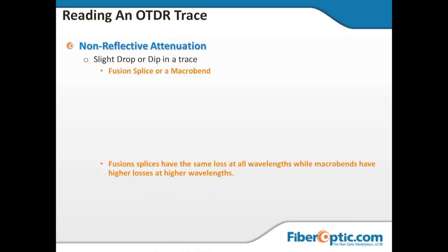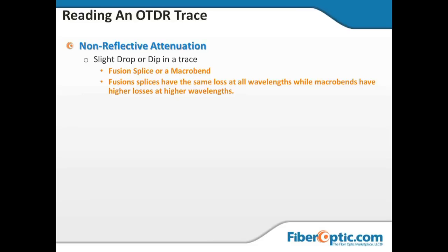And that's why a lot of the construction testing that we do behind splicers and construction people, when we're called out to do that kind of testing, is we will shoot 1550 and 1625 so that we can see where the bends are occurring, so that when someone decides they're going to use the entire spectrum with wavelength division multiplexing, they know that there's not any problems with bends that will show up later down the road.